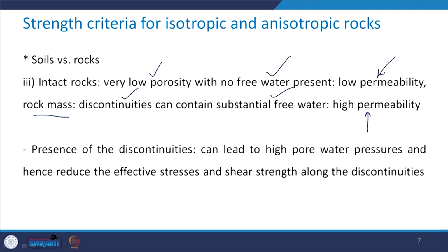Presence of the discontinuities leads to high pore water pressure, and therefore it reduces the effective stresses and the shear strength along the discontinuities. In the presence of water, the shear strength of soil also gets altered, but the way it gets altered is altogether different from that of rock.